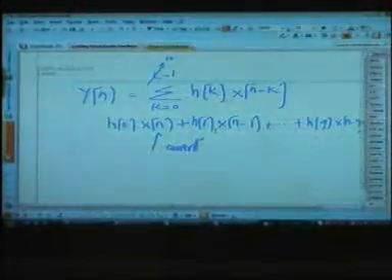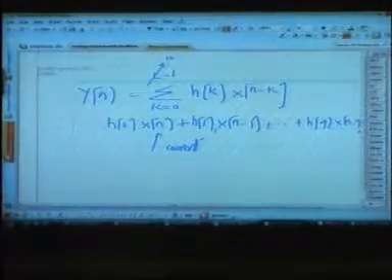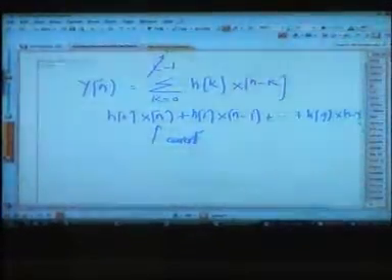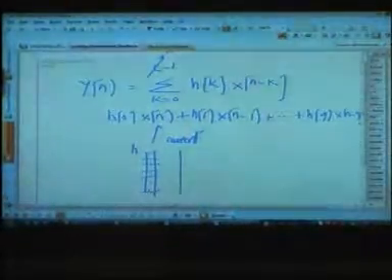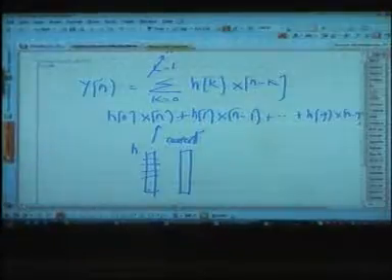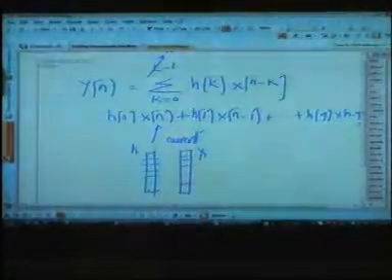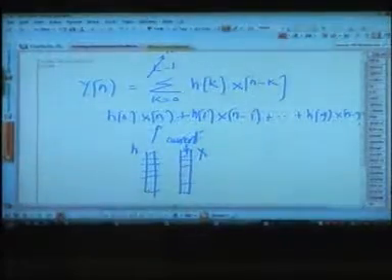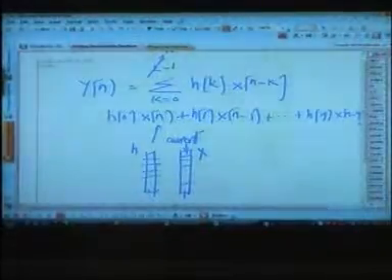If you are doing it in software, it's quite challenging as a matter of fact, because every time you get new data, you have to shuffle your array or use circular buffers. But all this algorithm is doing is taking an array of constants. There are 10 constants, and you call this h buffer. To implement one instance of the summation, one output value, you have this array y and x. X also has 10 values, but this is a dynamic array which is changing all the time. Every time you add a new sample, it gets into this location of your x buffer, and the old value gets out of this buffer. We also call this a tap delay line.